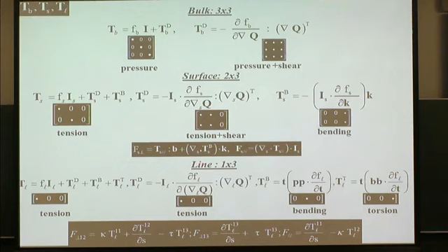And for the line, it's the same idea. So you have your stress tensor is 1 by 3. You have a tension from your line tensor and your Ericksen stresses. Then you have bending and torsion. Bending is the 1, 2 component, torsion is the 1, 3 component.